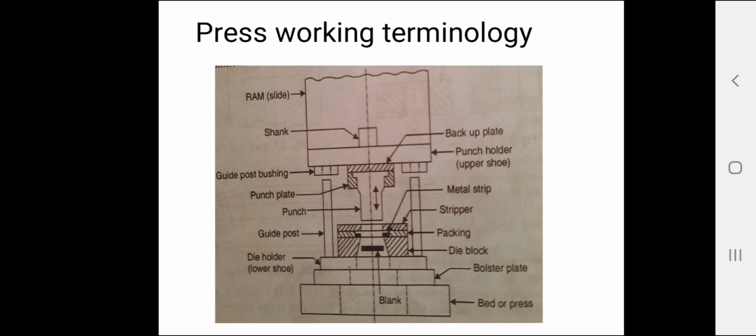What is stroke then? The stroke of a press is the distance of ram movement from its up position to its down position. It is equal to twice the crankshaft throw or the eccentricity of the eccentric drive. It consists of the crankshaft or eccentric drives but is variable on a hydraulic press.